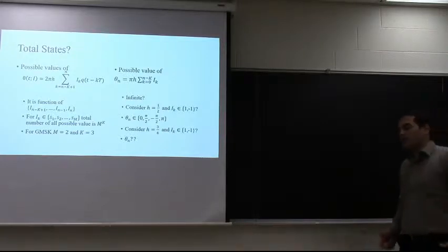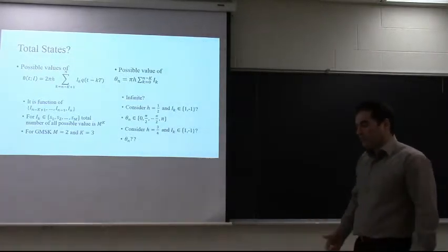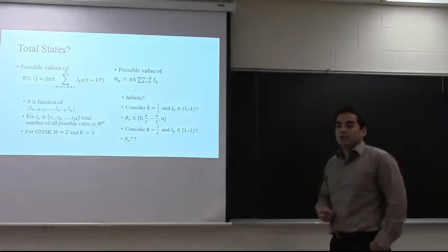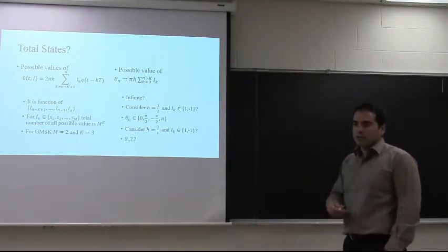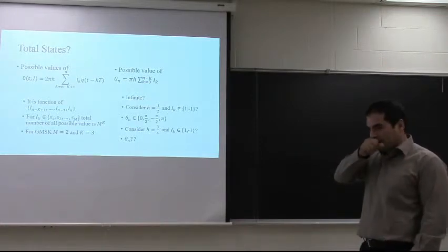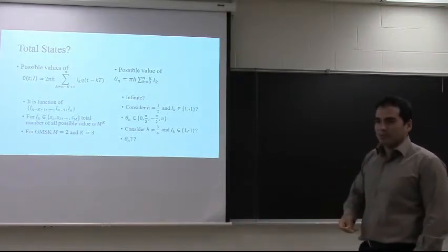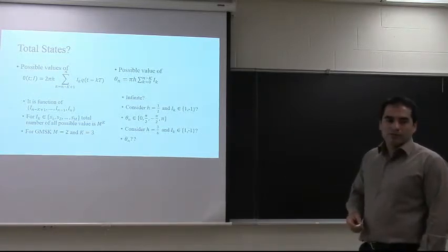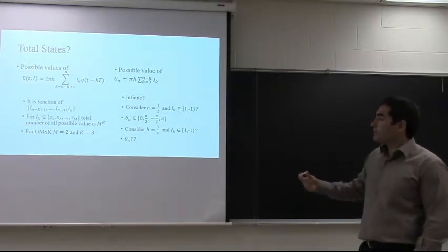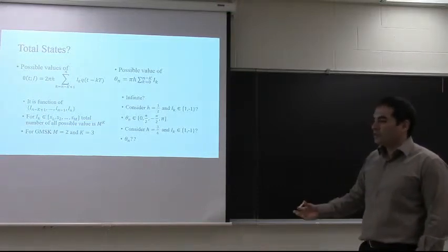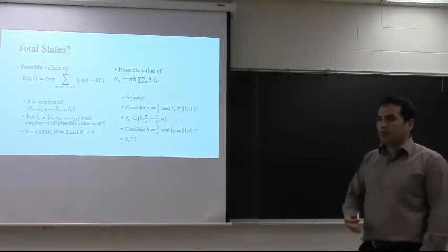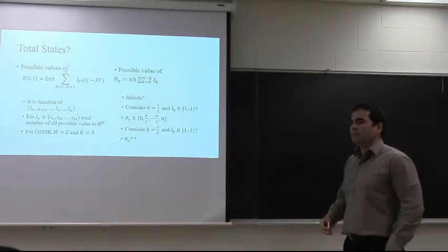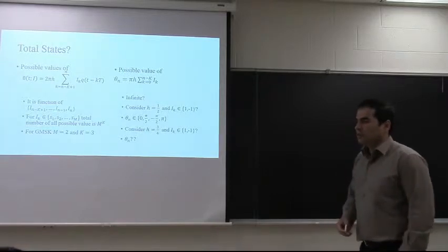Because if you are in an interview, claiming that you are familiar with GMSK signaling, CPM signaling, they are not going to ask you to solve this problem for me. They are asking about these details. You need to understand how to come up with the number of states of the Viterbi diagram for CPM signaling, over GMSK, over the fading channel. We will maybe discuss that too.